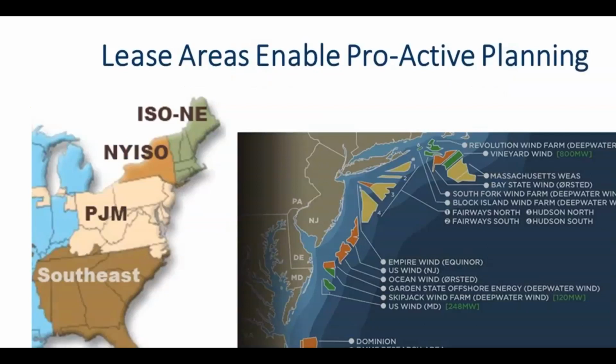And that proactive thing is actually quite easy with offshore wind. With the land-based wind, it was somewhat of a challenge with CREZ, with the Argos study in MISO that predated the MVPs. People had to go out and look at the interconnection queue, look at where the wind resources were, and say, okay, if we build the transmission, they will come. And luckily they did. These were good wind resource areas, and the generation did come after the transmission was completed. There's not that risk with offshore wind. These are being driven by state mandates. They have very precise quantities in certain years that are going to be deployed. We know where the lease areas are, so we know when and where and how much of the transmission and the generation is needed. And so the proactive planning is easier.